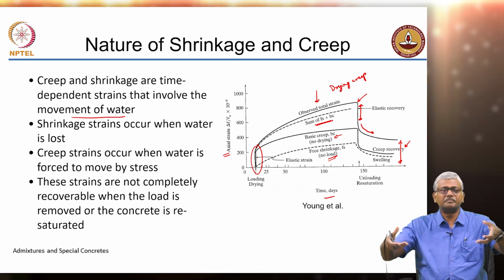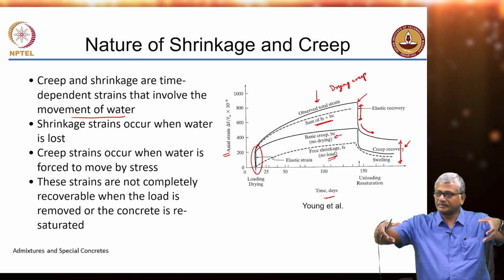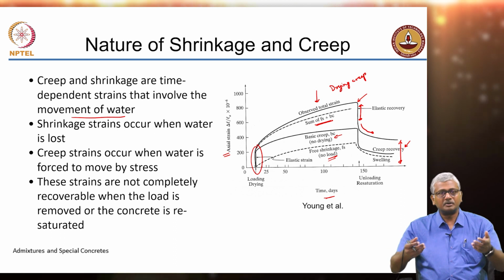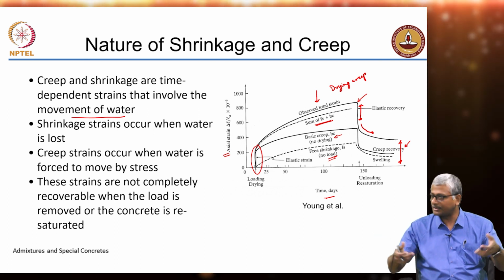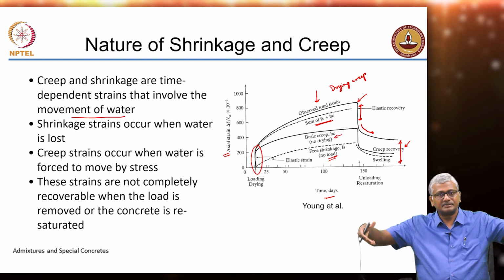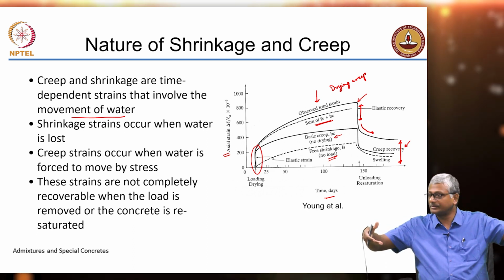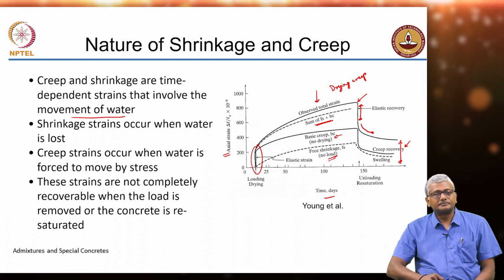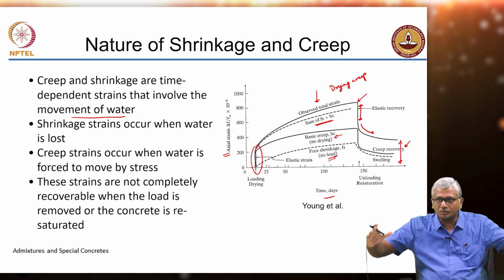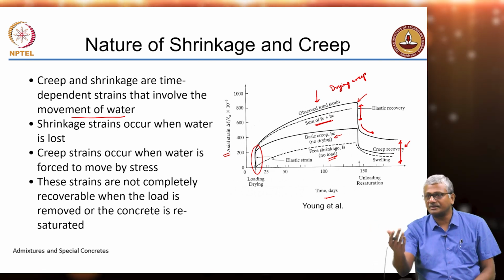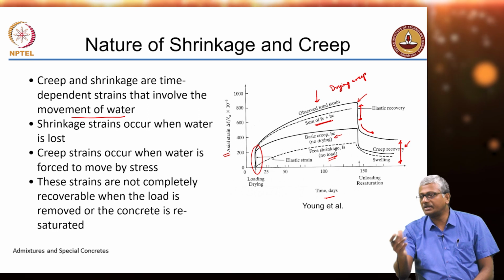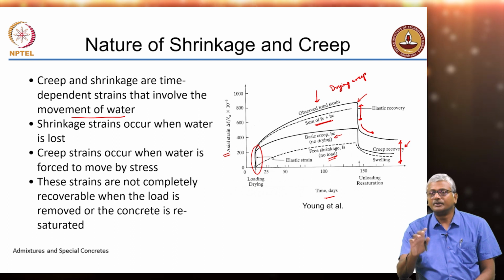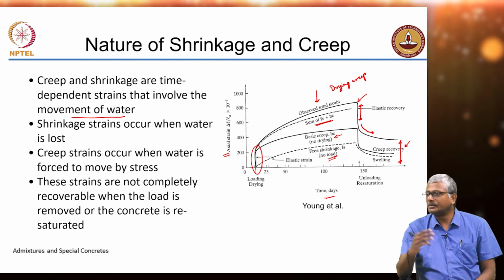Let us say a simply supported beam is bending like this. The bottom is under tension. Because of the effects of the load, the tension is only going to increase, the creep is going to increase the tensile stress or tensile strain rather, right? Creep is going to add to the tensile strain. But what about shrinkage? Shrinkage is trying to push the member back. So, there the creep and shrinkage are acting in different directions. So, depending upon the geometry of your structure and the way that the load is acting, you may have creep and shrinkage either acting together or opposite.